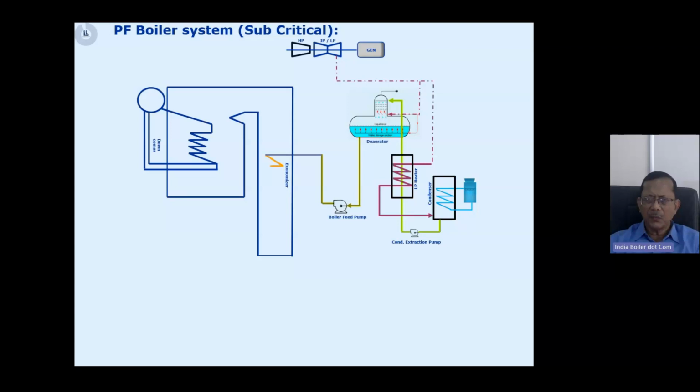From the BFP, the water goes through the boiler system, through the economizer, where the feed water gets heated, and enters the drum. Again, in a high pressure boiler system, the drum saturation temperature is pretty high, in the range of around 350, 340. So from a deaerator outlet in the range of 170, 175, 178, we need to reach anywhere near 320, 330 at the economizer outlet to get better steam generation in the evaporator.